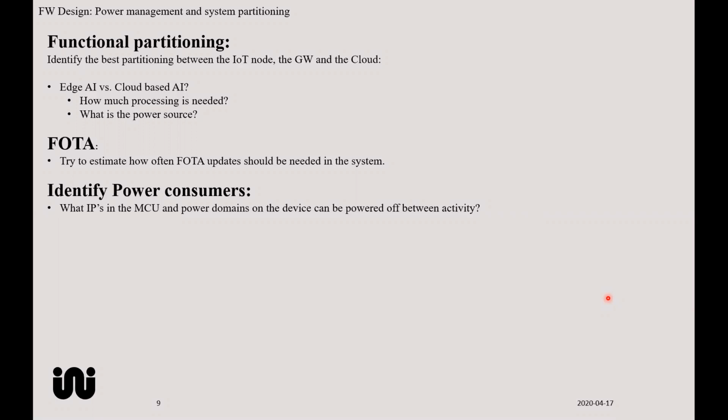You should, of course, not spend a lot of power on clocking a GPU, a graphical processor, if you don't use that. You shouldn't even clock a UART block if you don't use that. So each and every small block that you can stop the clock to will save power.